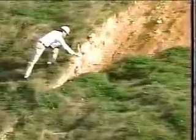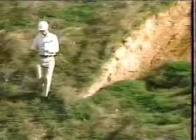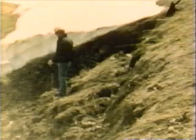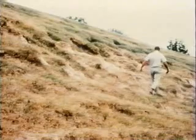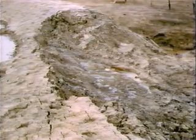Now, let's discuss the characteristics of slides that might occur on the upstream and downstream slopes of an embankment dam. Slides really fall into 2 categories: shallow and deep-seated. Shallow slides don't usually present a threat to the integrity of the dam, but they can lead to obstruction of water conveyance structures and to larger deep-seated slides. Deep-seated slides are usually a serious threat to the safety of a dam.